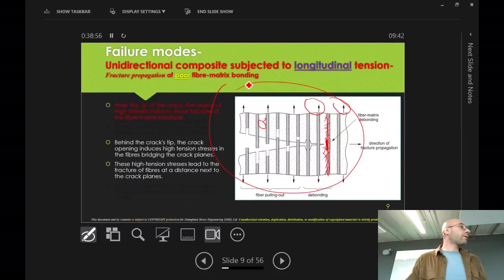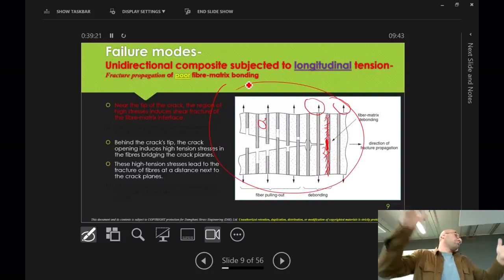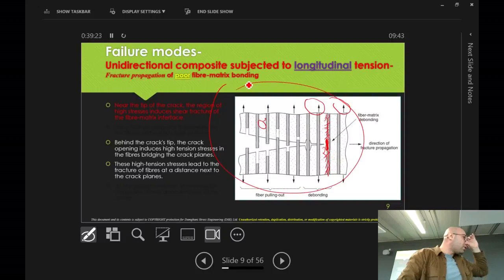Do you ever get a mixture between the two failures? Like some layers have poor bonding? Yes, I mean, it does happen. For example, if you don't have a clean room when you're prepping your composite, the dust might settle on one of the plies. That impedes the perfect bonding in that particular interface. And then the remaining plies might not have any dust or anything, even a tiny eyebrow hair, for example.